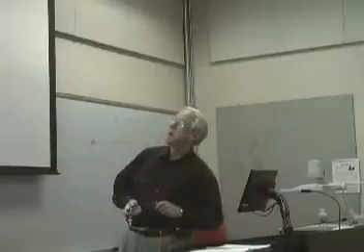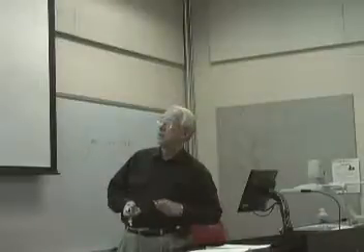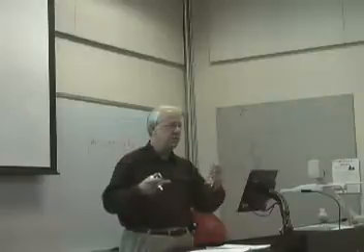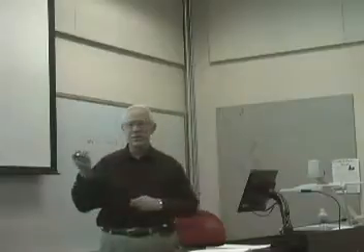Here's an example. Find N1 at node 1. Well, x is x1 and y is y1. I just plug it into that relation. N1 is equal to 0 at nodes 2 and 3. Plug into the little relations and what you discover, N1 is 0. The sum of all the shape functions, N1, N2, and N3, are always equal to 1. No more, no less. What does that remind you of when we said that before? Remember in polynomials, when we said, oh, the sum of these things can never be greater than 1. They're always equal to 1, the combination. That's the same thing going on here.